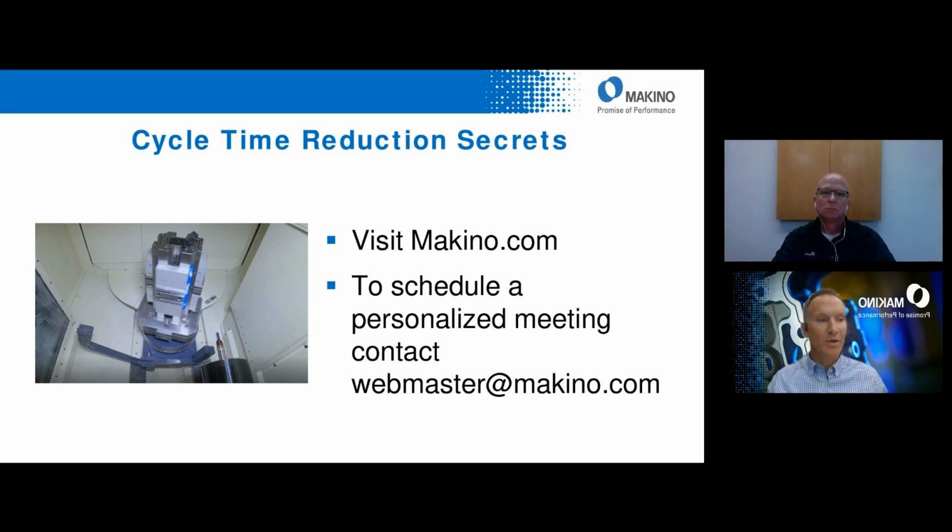What happens if you don't have that bit set to 0 as you specified? Unfortunately, it doesn't work, and you'll get a FANUC alarm. I think it's a tool compensation alarm. So it just won't let you do it. You have to split it out if you don't enable that parameter. So you'll get an alarm and get notified, hey, something isn't right at that point. That's right.